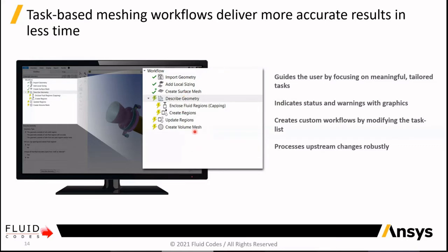And we can customize everything here. So if you are not happy about this workflow, eventually we can create our own workflow. So we have flexibility to change it. And when we need to change something, it's robust. So the moment I say, okay, I got the mesh, but I'm not happy because I need to change something, I'm not happy about the sizing, I want to change it. So let me go back, change this setting, and then update the mesh once again in one single shot.